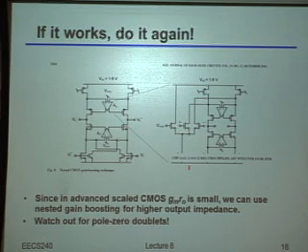Moving the pole zero doublets to lower frequency, you mean? So obviously it depends upon how exactly you've done the design in the first place. But really, I guess if you do it right, what you should be doing is adding more pole zero doublets outside of the bandwidths that you care about. Because again, if they're inside of the gain bandwidths you care about, it'll cause problems.